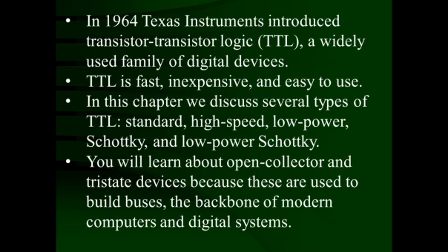And if this bunch of wires is going to be individually utilized, then a lot of wiring is required and the circuit becomes very complicated. To avoid this, a common communication path is developed. And depending upon the requirement, one of the peripherals is connected at a time with the MPU or CPU. This work is done by tri-state devices and open collector devices in TTL. That's why tri-state devices were developed, and that is very important. We'll see it in this particular chapter.